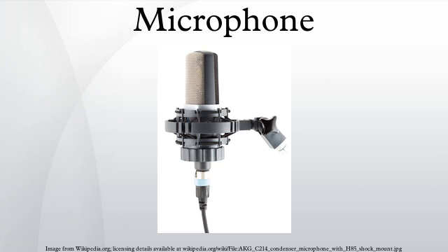There are two types, depending on the method of extracting the audio signal from the transducer: DC-biased microphones, and radio frequency or high-frequency condenser microphones. With a DC-biased microphone, the plates are biased with a fixed charge. The voltage maintained across the capacitor plates changes with the vibrations in the air, according to the capacitance equation, where Q equals charge in coulombs, C equals capacitance in farads, and V equals potential difference in volts.